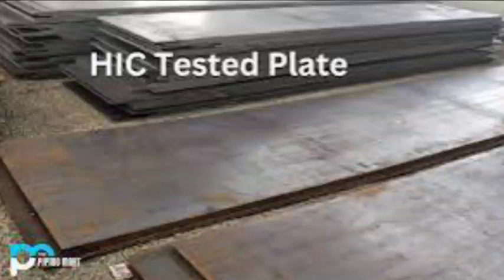Okay, now the plates are plates. Even though you control the sulfur to 0.003 weight% as per NACE, you have to mandatorily do HIC testing because they are most vulnerable. Okay, so they have to mandatorily undergo HIC testing. Is there now any? Go ahead.